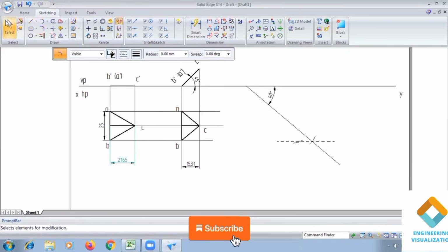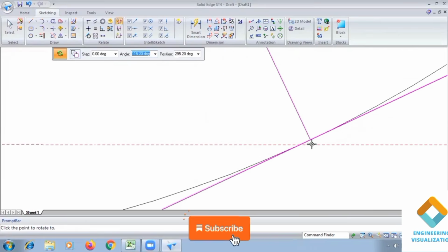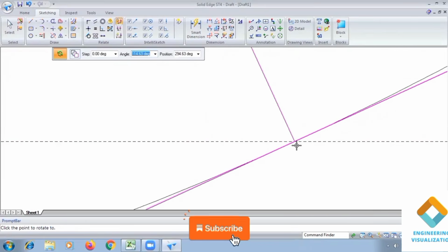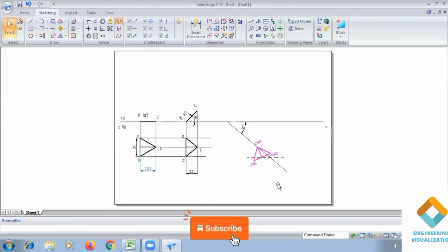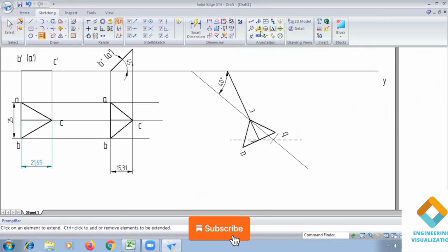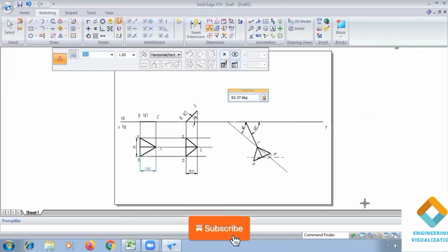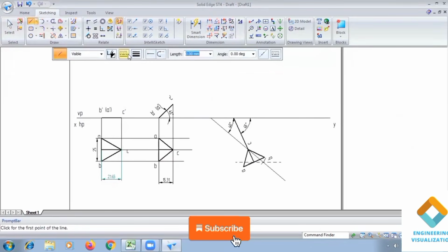Okay, now join. So just take this move command, take this reference point, so place it on this reference point. Go to rotate command and take this length and rotate and place it exactly here. Yes, zoom in and place it. Okay, now extend this angle line so that you will get beta angle. So this is the procedure, guys, to get the beta angle. Okay, so now project it further to complete the final position.